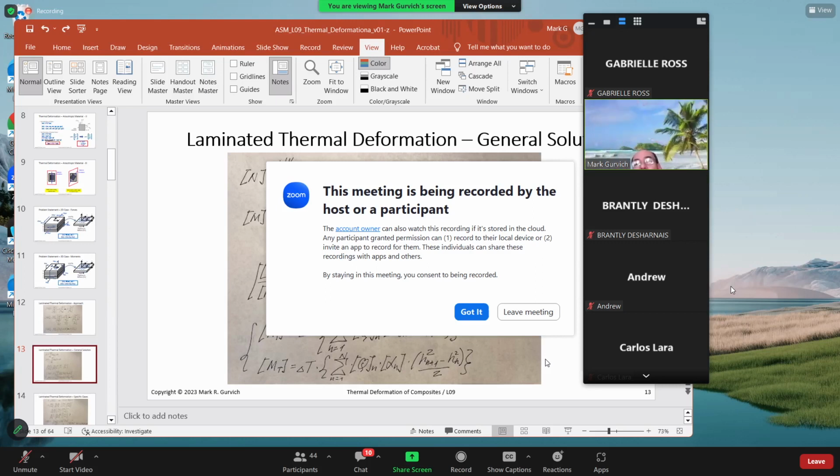If it starts to buckle and bend, it will cause damage, but most important, it destroys the accuracy of all this optical system. For an optical system, geometrical tolerance is really super important. So what we proposed was to optimize the structure to make an artificial imbalance.